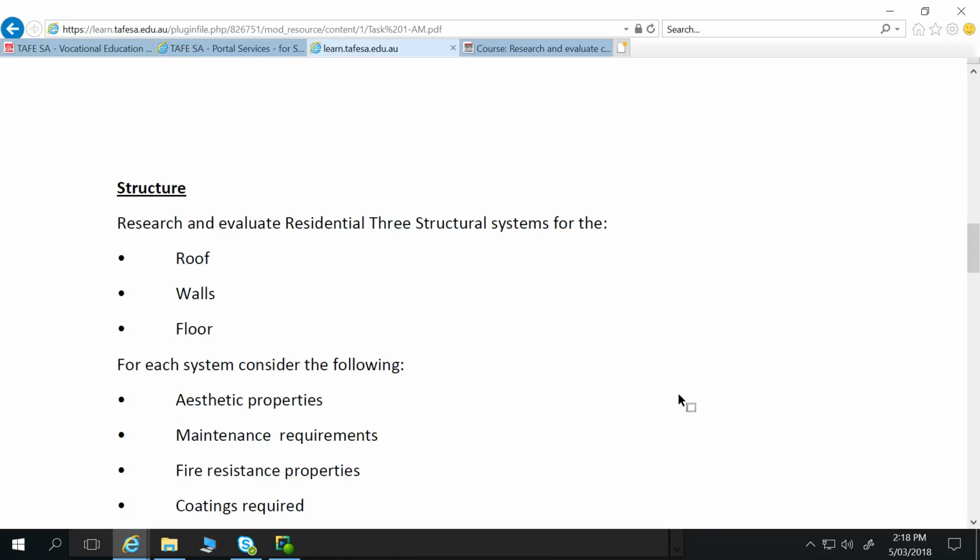There are issues. There was a building built in Melbourne using CLT, but the company that produced CLT and tried bringing it into Australia has had some issues, because it's basically around the timber supply, and the properties of timber that we grow here differ from the density of the timber that they grow in Europe, and it's about being able to maintain that strength, which they can't do with the product in Australia.